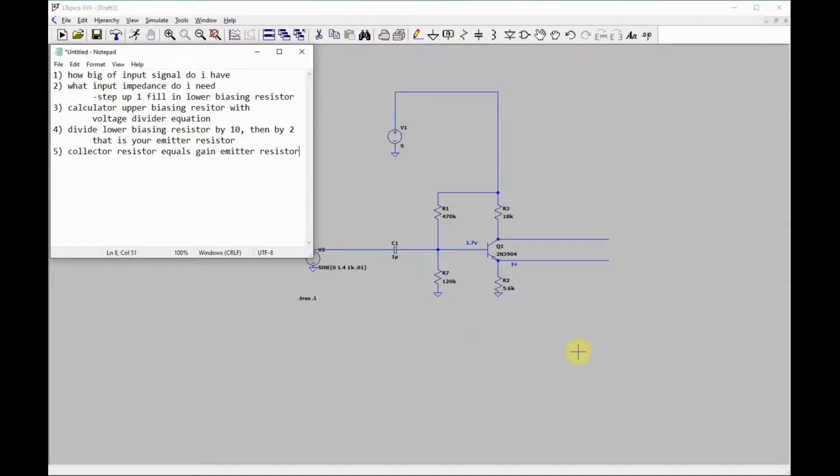So you just basically take this, multiply by the gain, and how much gain you can have is dependent on how much space you have. Like I said, if you have, this is going from 0 to 2 volts, that leaves you 7. 7 divided by 2 is 3.5. 3.5 multiplied by 5.6 gives you this 18.